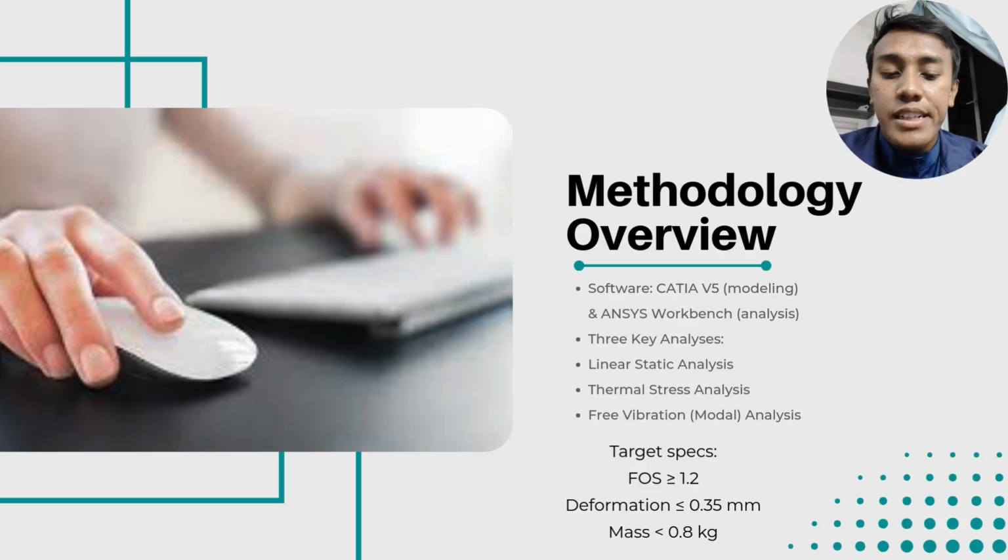Our target specs are: factor of safety is more than 1.2. Total deformation is less than 0.35 mm. Our mass is less than 0.8 kg.